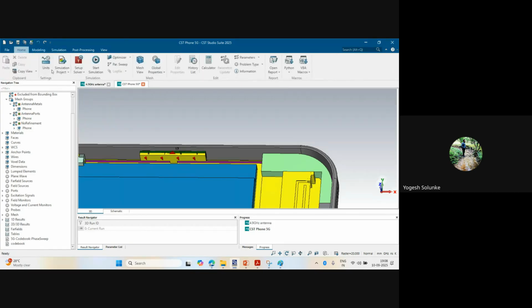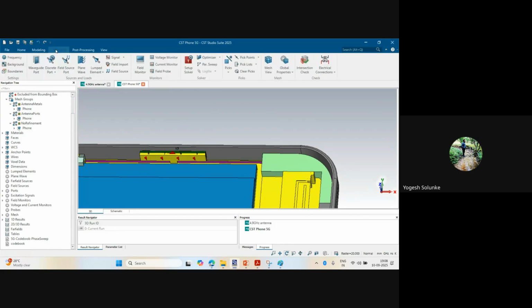To extend that, again, we have to use this task, and you need to do the scaling, wherein your input 1 watt power will be scaled to something else. If you want to give 15 volt or anything related to that, you do the RMS calculation and then do the scaling. But here, with the help of this discrete element, whatever voltage you want to give, you can assign it straight away.